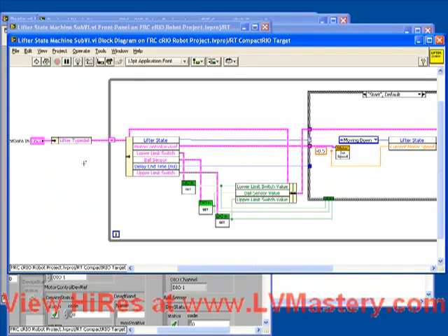What we're going to do is add a manual override mode, where a joystick button is going to turn off the state machine, put it into a manual mode where the joystick axis is going to move the motor speed of the mechanical lifter. This is going to make this example a lot more complicated, not only because we're adding states and modes to this state machine, but also because the Tele-Op.vi is where we're reading from the joystick. And that's where we need to write information that's going to come into the lifter. So let's look at how we're going to do that.